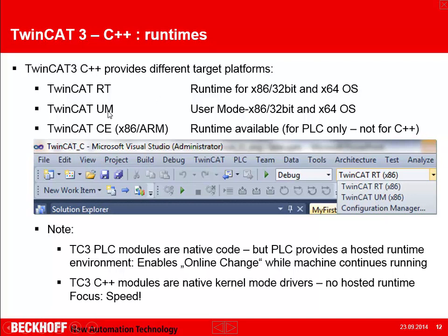We have something which is called user mode, but it's not enough to only select user mode here. You also have to start Visual Studio in a different way, and in this case you have to contact your local Beckhoff person. This is just for very specific companies writing a driver, accessing, for example, the DPRAM to make their own driver for their own hardware card. In this case, you deal with pointers, and you want to run that first of all in user mode instead of later in the hard real time. User mode is not providing hard real time, so it's just a development help.